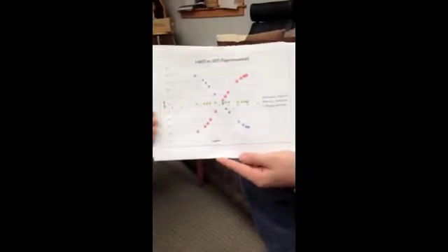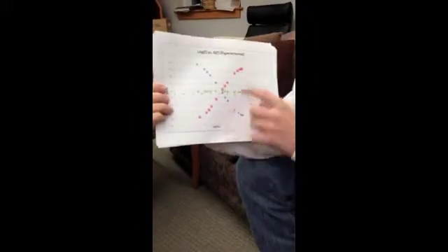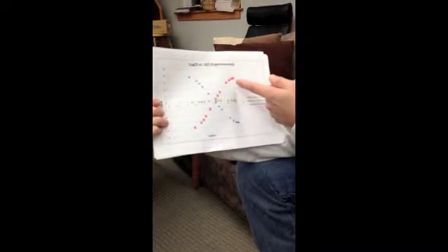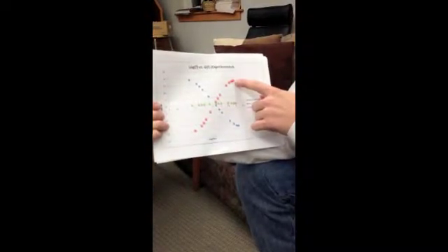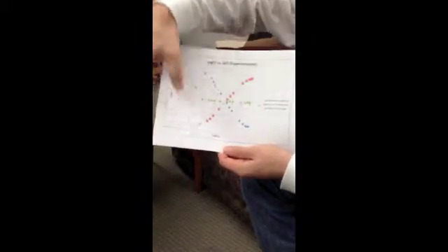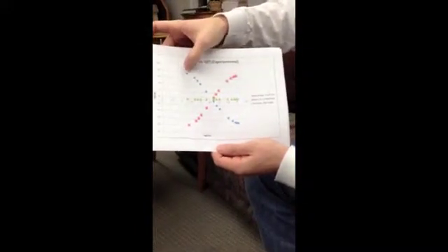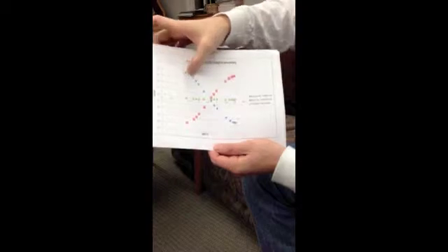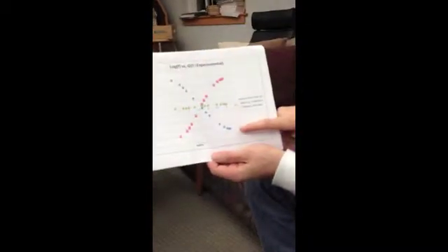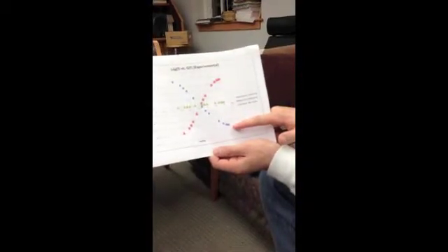This is proof that the previously demonstrated circuit design actually functions as built. As you can see, for the treble boost and the bass cut, it has a high gain of just under 20 decibels for high frequencies, and strongly cuts off the lower frequencies. For the bass boost and the treble cut, the opposite is true, with low frequencies having a high gain, and that declining down to a large cut for high frequencies, sorry.